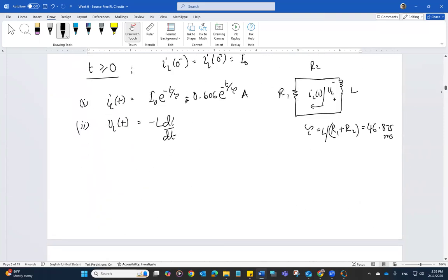All right. So it's the same thing as the capacitor: voltage cannot change instantaneously. So the capacitor voltage, if you're charging a capacitor, positive is on top. If you remove the source, positive will still be on the top. However, the current direction is going to change, and the capacitor starts acting as a battery. So current starts coming out of the positive side.